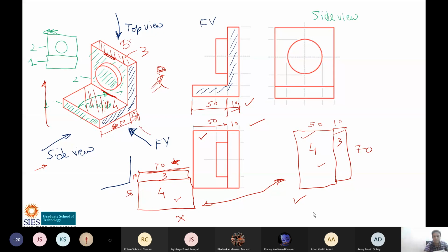Okay, hold this. Now what is this rectangle? What do you see? You see a rectangle. Apart from this edge, you also see some of this surface. But since we are considering that the rays are parallel, we will ignore this. We do not see this, because it will be seen from the side view. If you are looking at this object from here, then the front view will show only this edge. If I keep it like this, then you can see a bigger rectangle in the front view.